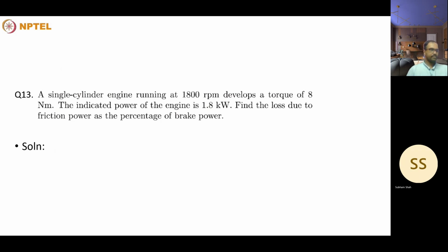In this particular problem, this is a simple question. We can calculate it by using the standard formulas available. We can calculate the brake power from the torque of the engine. And using the brake power, we can calculate the friction power as the indicated power is given in this problem, and then we can calculate the friction power as a percentage of the brake power.